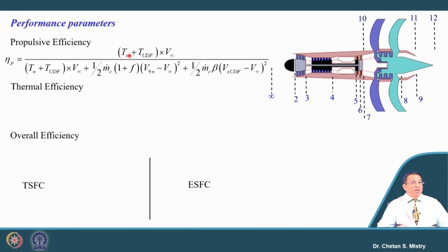If you recall, we had a similar kind of discussion for the turboprop engine, but when we were discussing the turboshaft engine, where our sole purpose is to generate power only, the thrust term was not coming into the picture. Similarly, here we write total thrust into V infinity, and this represents the kinetic energy for both our core engine as well as the bypass configurations.